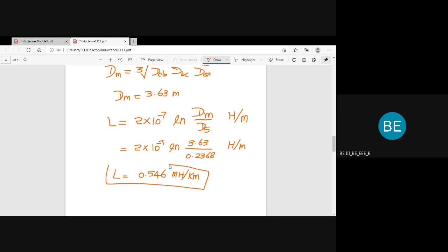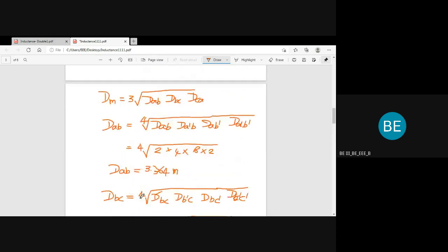So the horizontal arrangement is somewhat easier than the vertical arrangement. In the vertical arrangement, we have to find some conductor distances through triangle methods. Here there will be no such issues. We can straight away read the distances between conductors easily by looking at the picture.